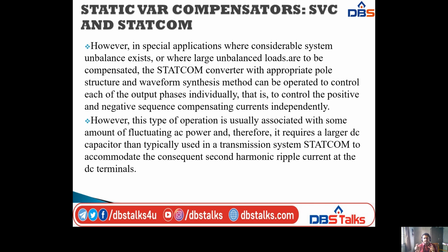However, this type of operation is usually associated with some amount of fluctuating AC power, and therefore it requires a larger DC capacitor than typically used in a transmission system STATCOM to accommodate the consequent second harmonic ripple current at the DC terminals.